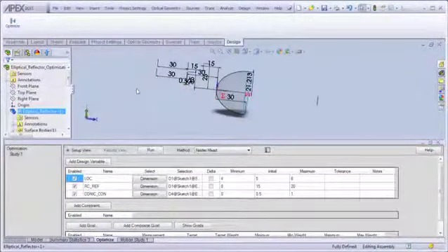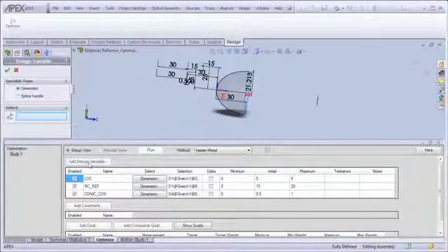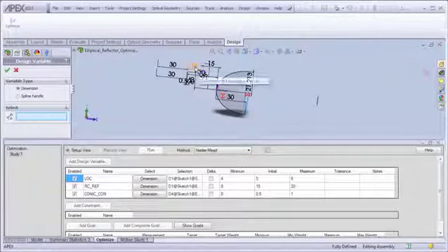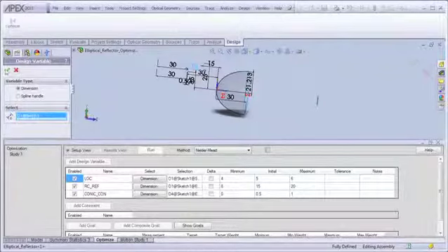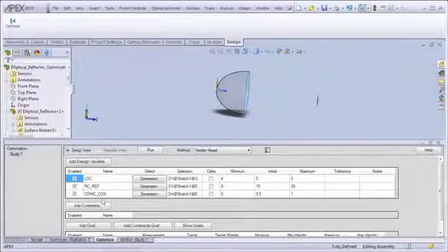In order to add a design variable, click the Add Design Variable button. You can then find within your sketch that variable you'd like to add, highlight it, and click the checkbox, and that variable will appear in the Design Variable table. In the Design Variable table, you can rename the variable, and you can also set the minimum and maximum values of that particular variable. If you check the delta box, you will get a value which is on either side of the initial starting value as a minimum and maximum value.